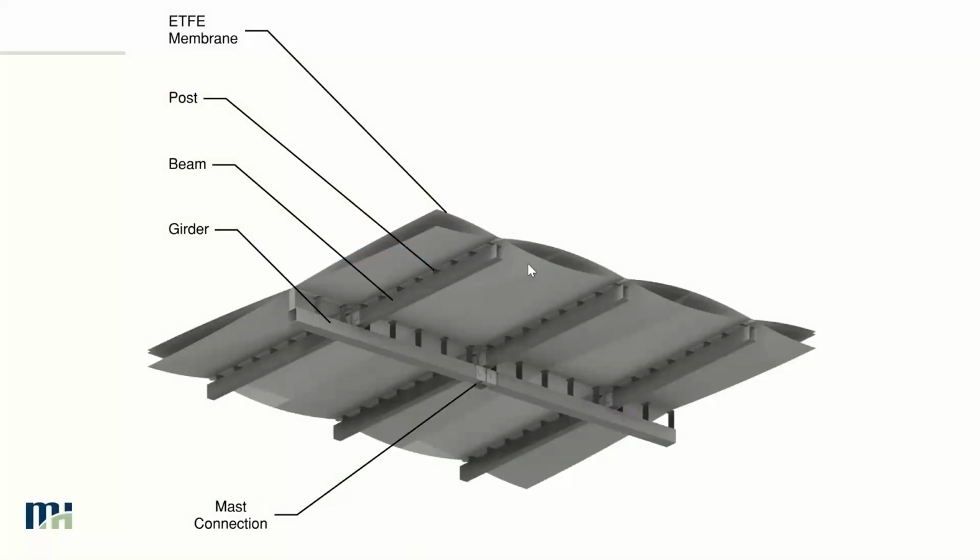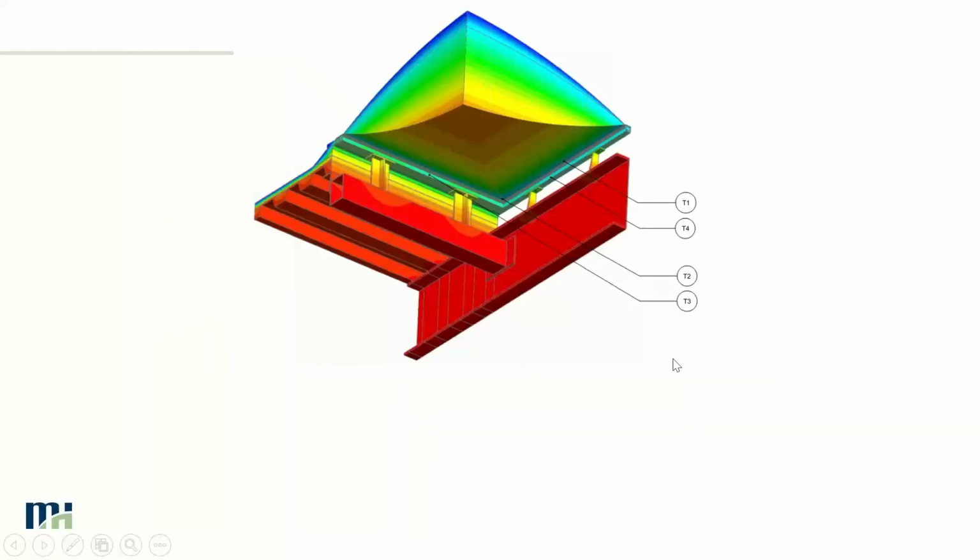Similarly, we can take a look at an ETFE roof. In this case, where is going to be our coldest or critical temperature location? Looking at one section of this roof area, we can see that you have these large I-beam structural connections, and then you have these little struts that help stand off the ETFE framing off the main structural support. So right up against the framing is probably where our coldest temperatures are going to be.